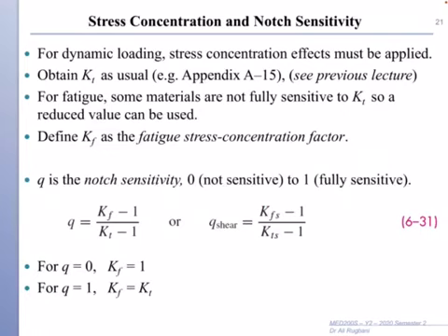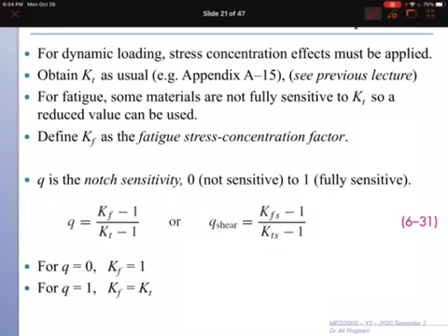You know that there will be stress concentration if there's a change in dimensions, any change in surface, any groove, change in diameter, any hole, any notches. If you have these situations, then you need to include the fatigue stress concentration factor, Kf.